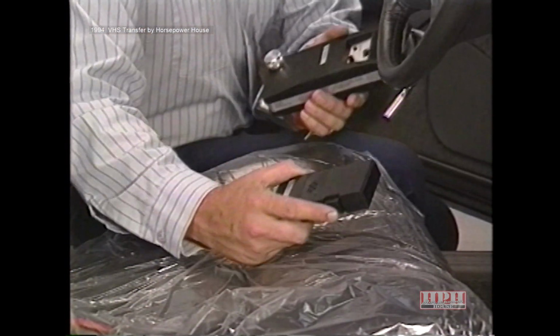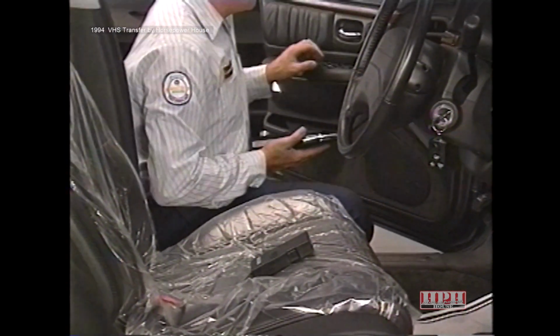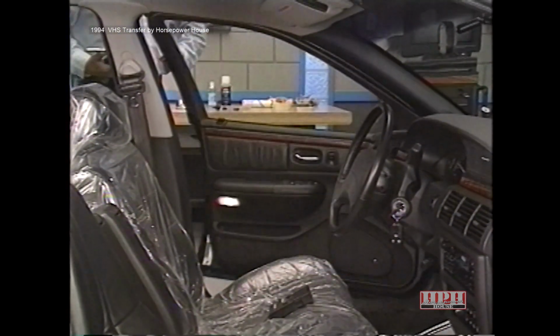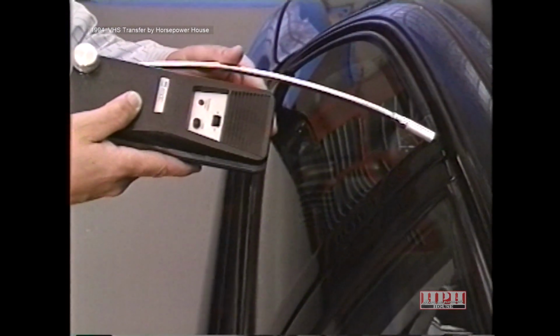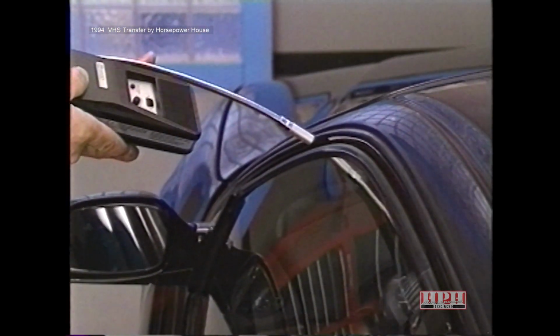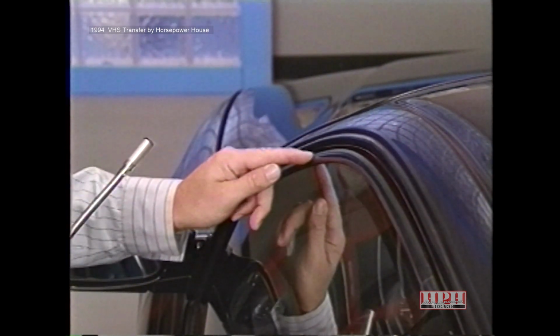Now, if you're using a two-piece electronic leak detector, place the transmitter in the vehicle. Then close all the doors and windows and allow sufficient time for the interior pressure to build up. Once the vehicle is pressurized, inspect around all edges of the doors and windows using either the detecting unit of the electronic leak detector, an audio tech probe, or the stethoscope to listen for a leak.